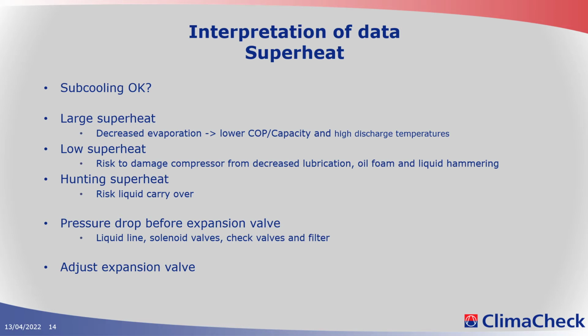Of course, if the pressure ratio is too low for the design of the expansion device, the superheat will also increase. Also, unstable expansion valves are quite common, and in many cases they might not have been checked for proper operation over the whole envelope.